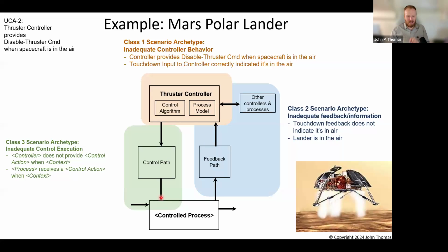But because its previous command had latched down here in the control path, as soon as that software interlock was removed, which was from the radio altimeter, as soon as it gets below 40 meters, that software interlock is removed, and the previous command from long ago now gets through and executes, right? And so this is a legitimate case to think through, right? It gets more interesting than just simple failures.